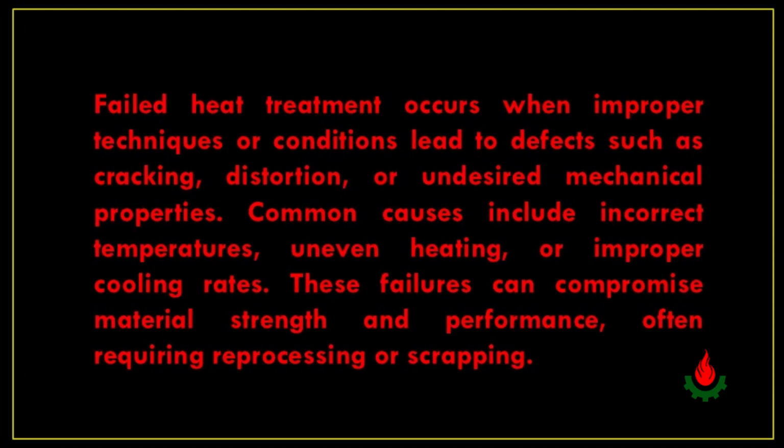Failed heat treatment. Failed heat treatment occurs when improper techniques or conditions lead to defects such as cracking, distortion, or undesired mechanical properties. Common causes include incorrect temperatures, uneven heating, or improper cooling rates. These failures can compromise material strength and performance, often requiring reprocessing or scrapping.